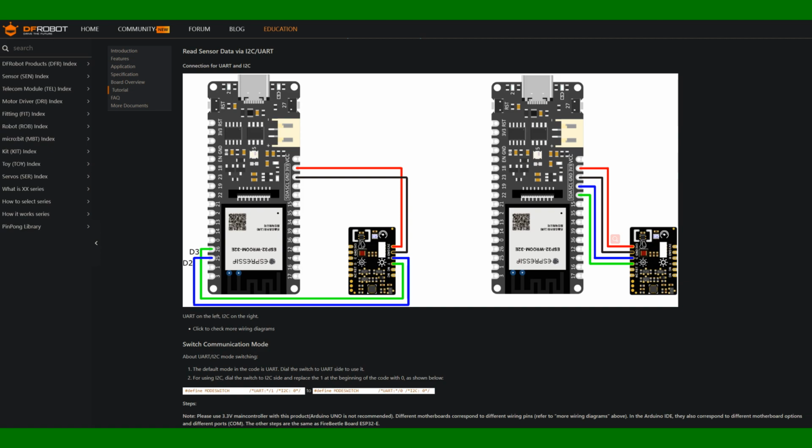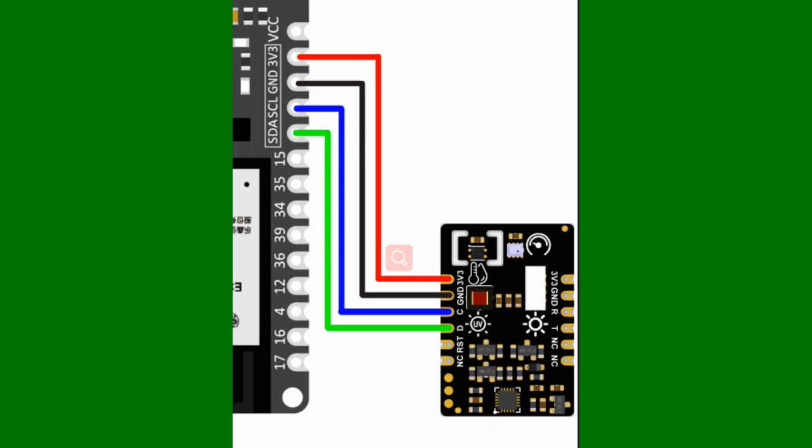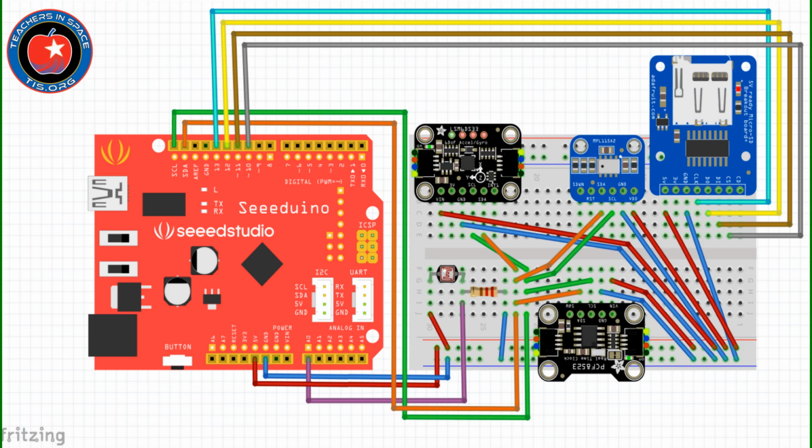Do you have any questions? So as far as the wiring, since you said that it works with the same setup that we had before, we should not encounter many issues while connecting this. Okay. Nope, it's really that simple. It's only 4 wires that you need to hook up. It's very similar to most of the sensors that we worked with in the workshop. If you go back and look at those, it was just 4 wires for almost every single sensor. It's power, ground, and then the SDA and the SCL. That's it.